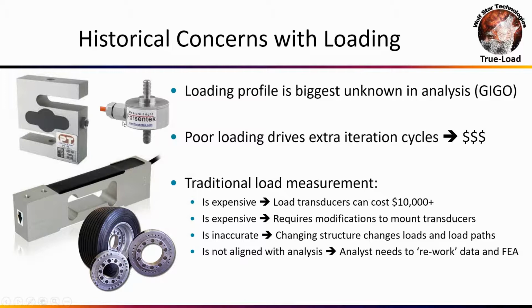So people try to get a better understanding of the loads using load transducers like you see here, and these are fine, but the problem is that they're expensive. And every time you use one of these, you've got to modify your structure. You've got to cut out part of your structure and insert the load transducer. So now you've changed the stiffness, you've changed the mass, and you're measuring something that may or may not be the actual loads. And now the analyst, who is typically working on the as-designed part, has got to rework their FEA model to look like the test part in order to use the loads you just measured. So this isn't great, but this is traditionally what people have had to do to understand loads.